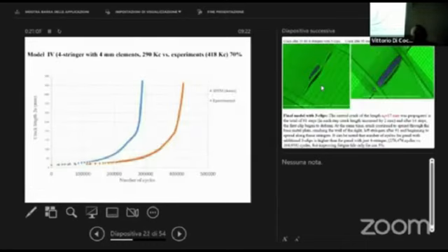If we compare these results with the experimental ones, then we can see that 290,000 cycles versus experimental data, which is 418,000, is not really the best that we could get out of this, but it is at least conservative, and we decided to keep it this way. There are a couple of possible explanations why this estimation is around 70% of the experimental results, but I will not go into details, at least for now.